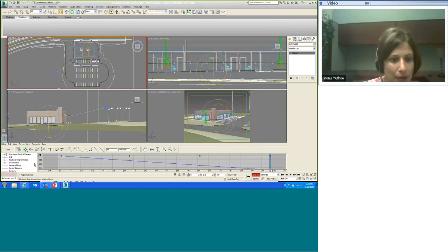We can move down and locate our dummy object. So as you can see, I go into objects and I locate my dummy object and the transforms that I've applied. I have applied the select and rotate transform to it in the animation. And here you go, these three rotations have been selected, and the curve for it has been displayed in the curve editor.